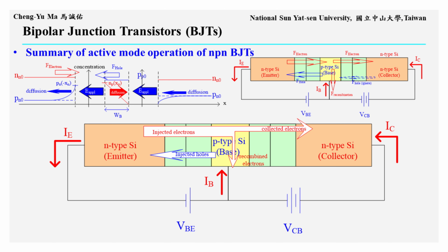The hole current mainly occurs at the base emitter junction, where holes are injected from the base into the emitter under forward bias. The very small hole diffusion current from the collector region can be ignored. As a result, the emitter current IE is defined as flowing out of the terminal, while the base current IB and collector current IC are defined as flowing into the device. For IB, both the electron current contribution and the hole current contribution are into the base terminal. For IC, the electron current contribution is also into the collector terminal.